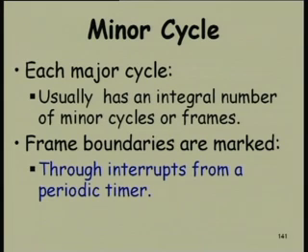We will see that unless it divides, the table size becomes large, because we can't repeat the table until the major and minor cycles complete at the same time. So the table size becomes very large, more than LCM of P1, P2, Pn.